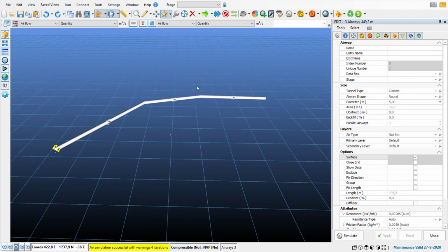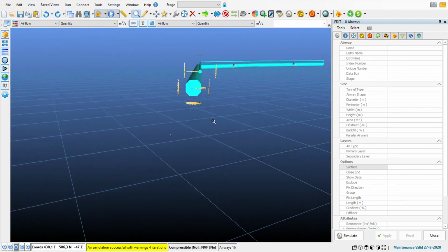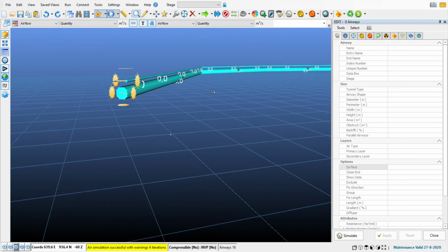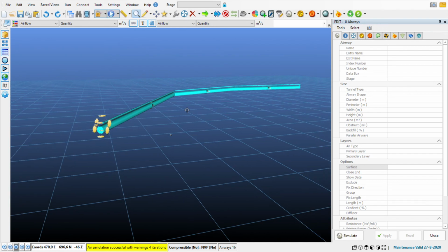Then here you can change the different parameters of the friction. You can even define leakage, so how much air is escaping the duct. You can also define the different air types. You can even analyze heat transfer. And so once you're ready, you can click on build duct, and you will see a little duct that is parallel to the tunnel. This is just a representation, right? The duct goes in the tunnel, but here is a representation of it.